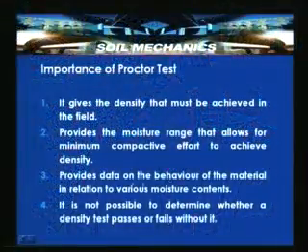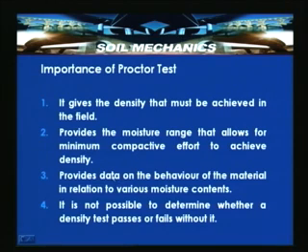It provides the moisture range that allows for the minimum compactive effort to achieve the density, and provides data on the behavior of the material in relation to various moisture contents. So it also gives us how the material behaves by varying the water contents. The behavior can be different for different soils. And it is not possible to determine whether a density test passes or fails without it.